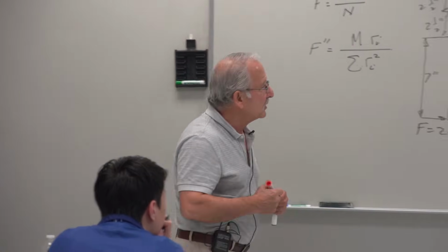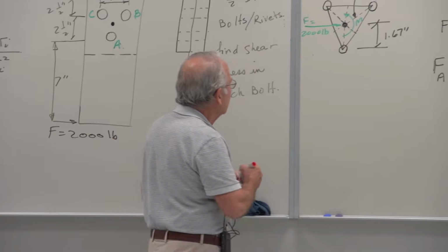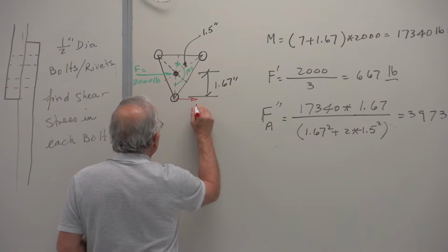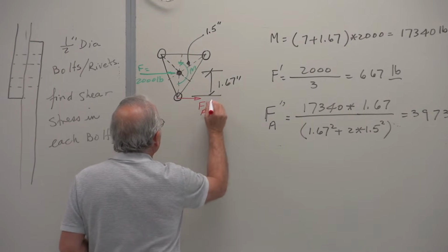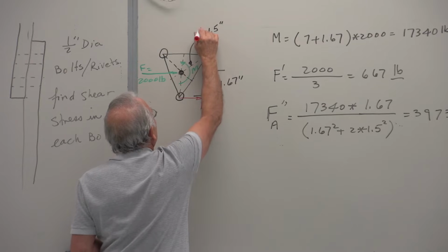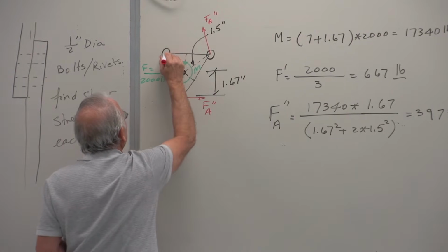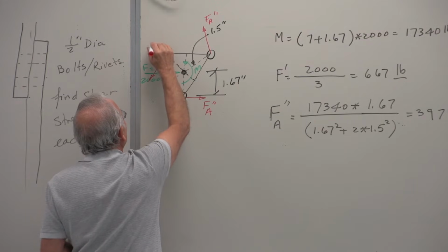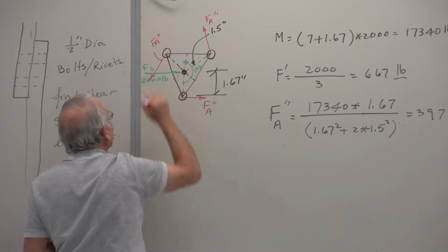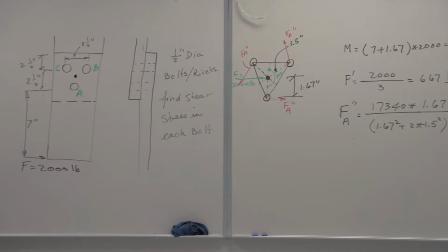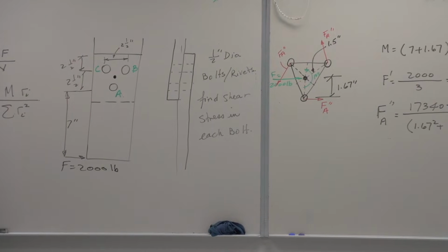So when you look at the forces that are applied here, they must be perpendicular to the line joining the center of that bolt and the centroid.